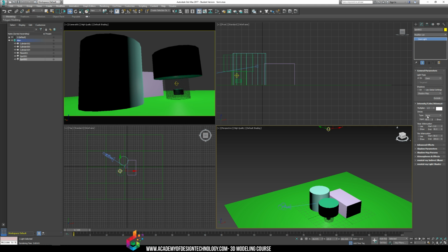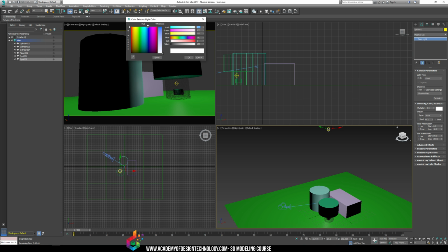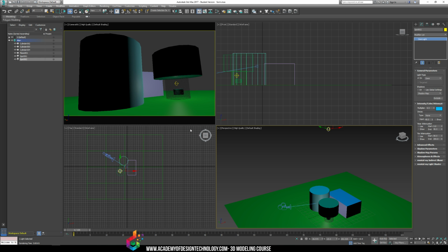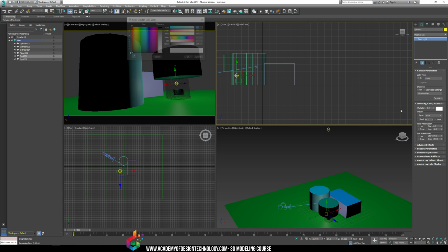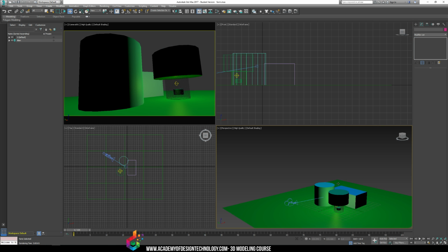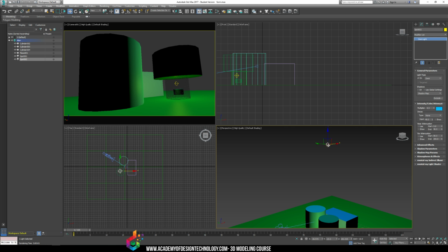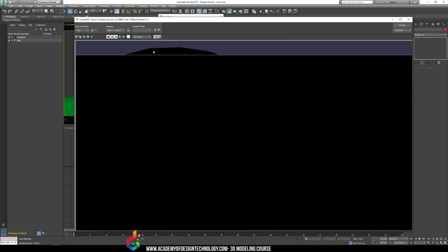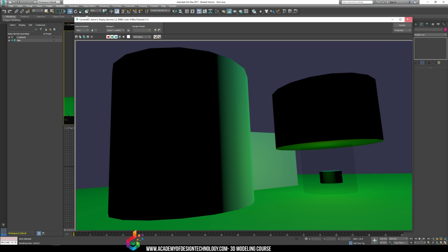So I'm going to create a really soft omni light up here, maybe 0.5. I'm going to make it blue. And then I'm going to make sure that this omni light looks green. So my tractor beam has a very green light at maybe 0.4. And I have a nice soft blue light in my scene. And I might want to even increase this a little bit, maybe 0.7. So we're getting a nice mood to our lights.